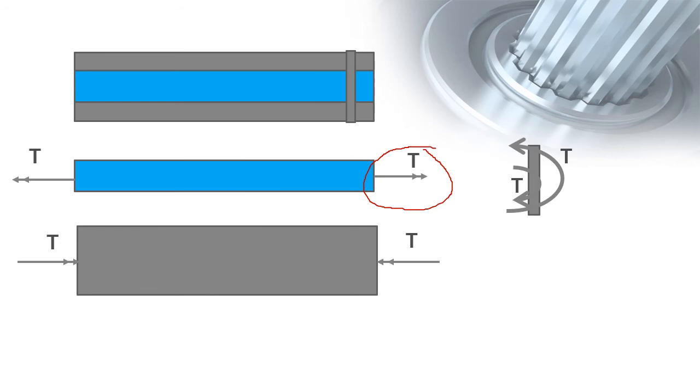Hence, from these diagrams, we have established that the torque in the steel is equal to the torque in the aluminum. As I've said, we would not be using the original equations that I stated at the start of this lecture. So for composite shafts that have an initial mismatch, where you remove the torque after aligning the mismatch, the torque in the steel shaft would be equal to the torque in the aluminum shaft after the removal of the torque to remove the mismatch.